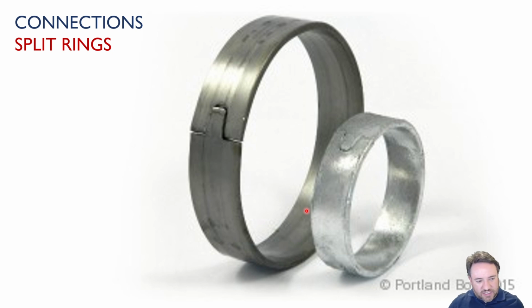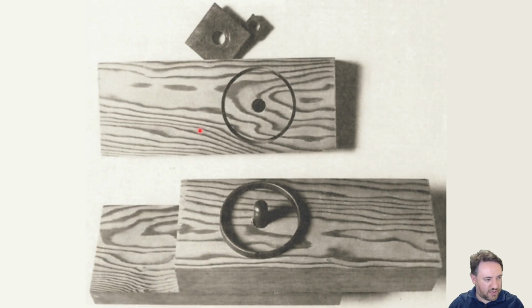Okay, this is something else that's in the standard that we're not going to talk about in a lot of detail, but I just want to make you aware, because it does have some good potential applications, is called a split ring. You can see it's a ring of steel, and the split is just that the steel is not connected all the way around. There's a disconnection here. So this split ring can actually open up and close up a bit. And that allows some flexibility on the size of the cavity that I install it in, as we're going to see in a second.